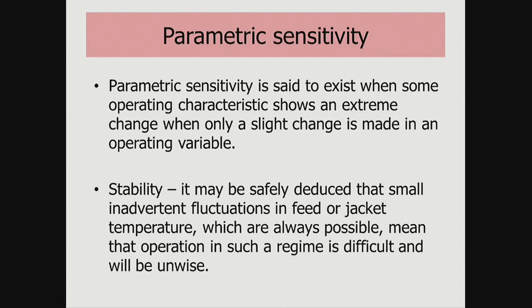Stability, it may be safely deduced that small inadvertent fluctuations in feed or jacket temperature are always possible, which means in an operation it's difficult to control, and without the right amount of control it will be unwise to operate. So in other words, if your design specialist says we're going to run at that temperature, you go no. And you go no because you've done some basic calcs that allow you to tell whether it's an exothermic sudden increase or it's in a stable region.